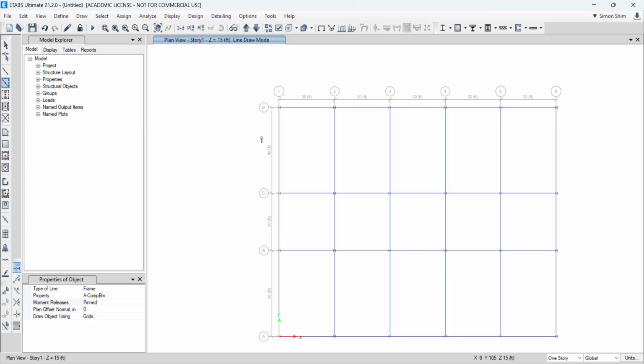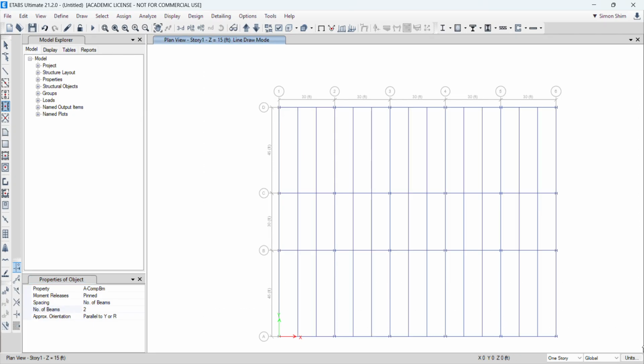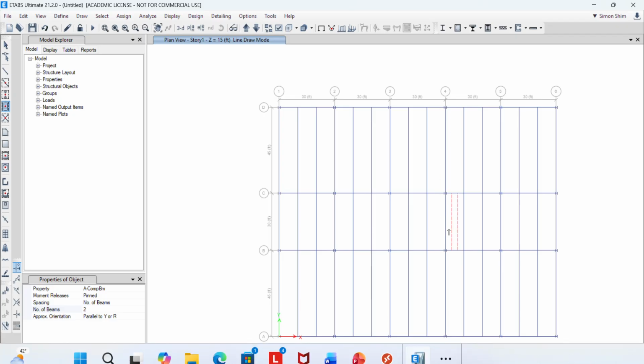All right, now filler beams. Here, let's see. Now quick draw secondary beam. Okay, if that works, pretty much okay. If you click this, it automatically shows composite beam, number of beams. Because this is 30 feet, right? So our beam spacing, we want 10 feet. Again, 10 feet. So I need only 2 beams, right? So this setting is parallel to Y. So if you hover around, it shows this, right? Oh, okay. I can click it individually. Let's see. Oh, it works too, right? Drag and drop. You can add all the beams.